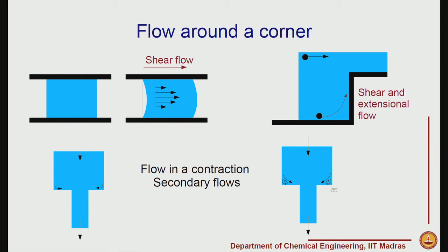So, what we have are dead zones which arise in this flow. These kinds of dead zones are also of great practical interest, because they should be avoided. So, let us say a car part is being manufactured, with some part of the car having a small thickness and some other part having a higher thickness. Then in a mold we will have such a contraction, where the polymer which is molten will be forced into these kinds of gaps, and then it will go through this contraction.